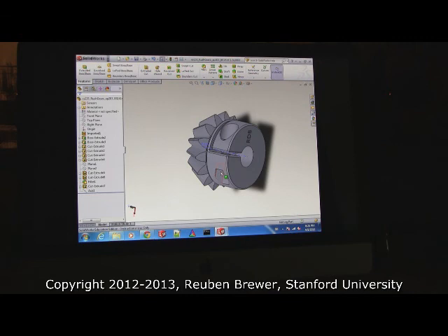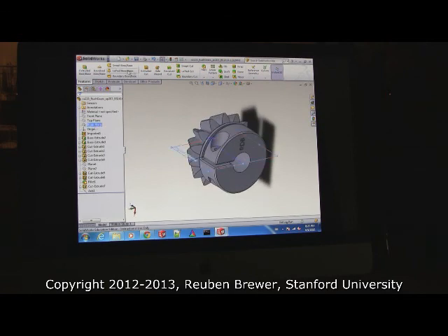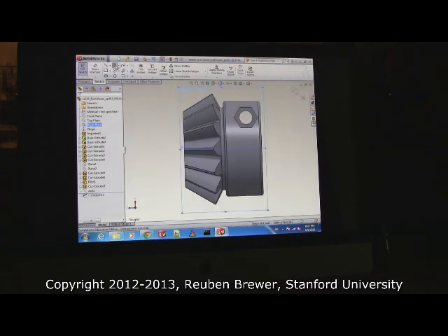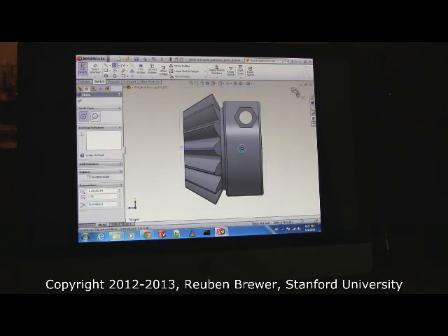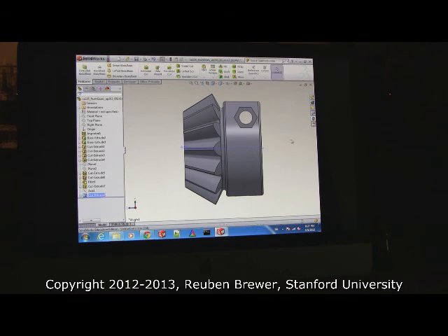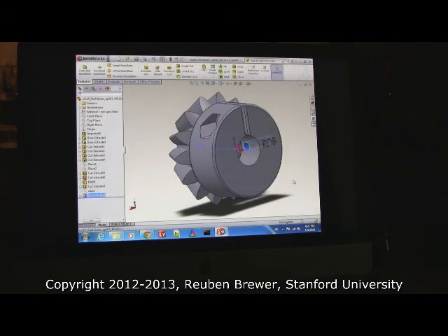A set screw is where you have a screw that drills into the side of the gear through the middle. So here, I'll just show you real quick. Don't do this. A set screw would be like a screw through that hole that screws directly into the shaft. They're annoying as hell. Try to use them as little as possible. If you use a set screw, you have to put a flat on the shaft so that you don't hurt the outside of the shaft, and then that's just more machining. Clamps don't hurt shafts, and you can tighten them with an Allen key super easy. They never vibrate loose, so that's why we're doing it. So is everyone clear on what we just did?